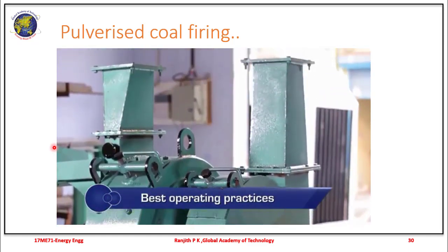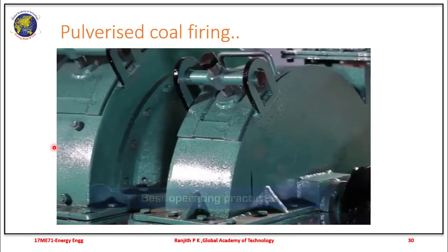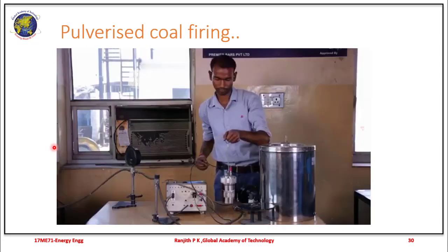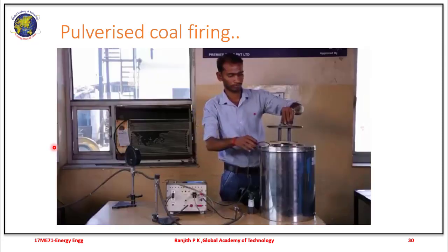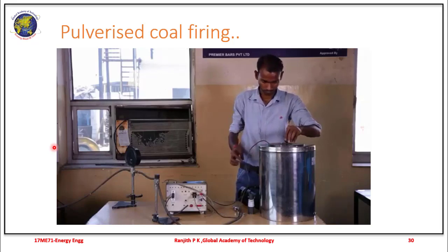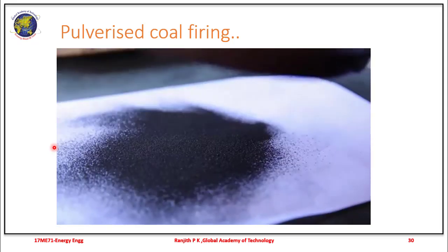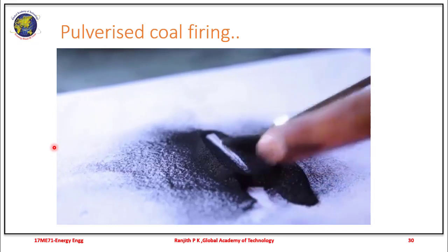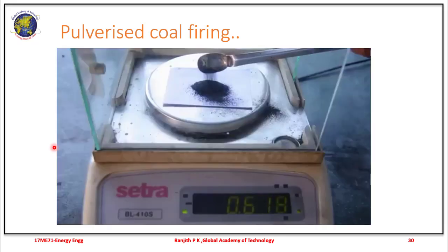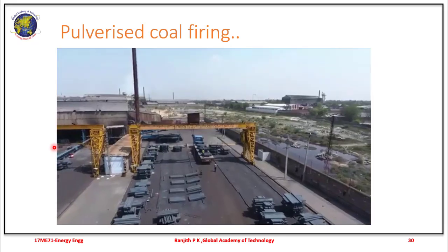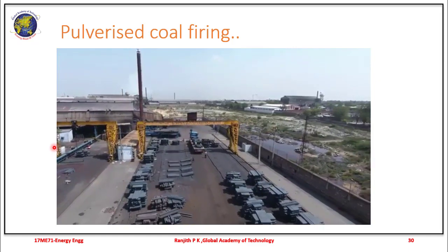For ensuring optimum performance, a pulverizer should be regularly maintained. The pulverizer components should be replaced periodically. It is proposed that a bomb calorimeter be used for in-house quality checks of coal. A metal sieve of -200 mesh size or 75 microns can be used for measuring the coal output.